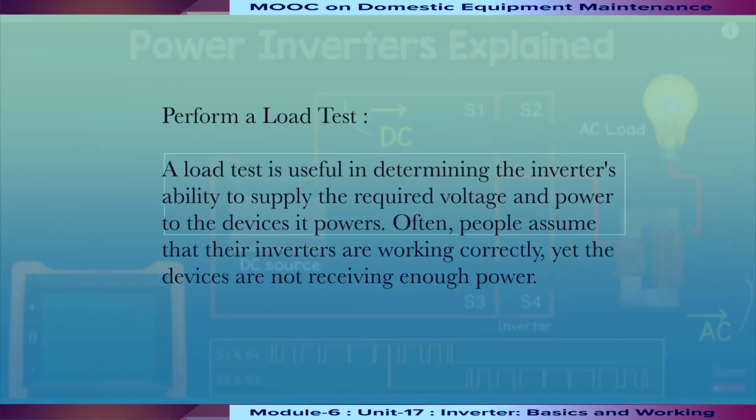Perform a load test. A load test is useful in determining the inverter's ability to supply the required voltage and power to the devices it powers. Often, people assume that their inverters are working correctly, yet the devices are not receiving enough power.